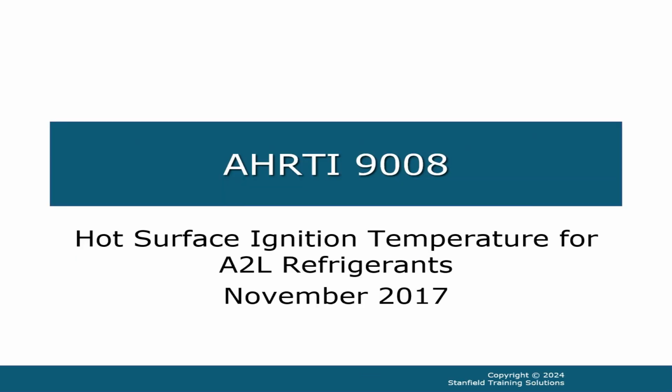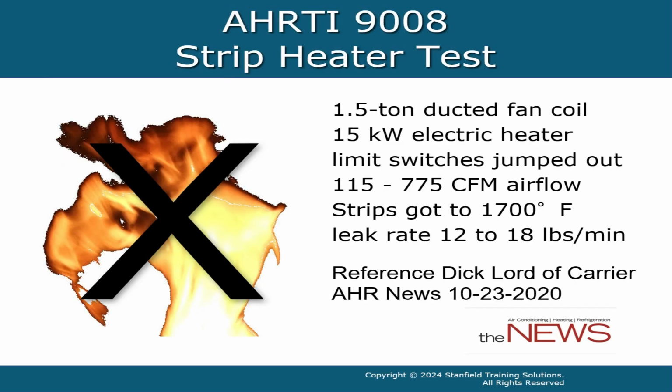While the AHRI 9007 test tested many different types of possible ignition, the AHRI 9008 test tests specifically hot surface ignition temperature for A2L refrigerants. It was conducted in November of 2017. One of the most common concerns about A2L refrigerant is the possibility of ignition from strip heaters. This is also fairly logical, so AHRI tested it in their 9008 test.